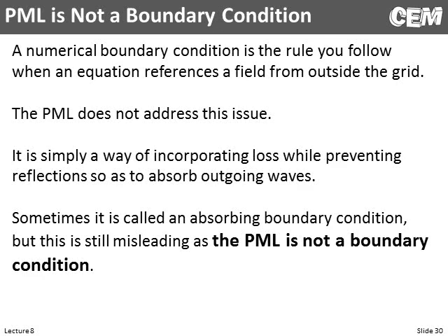The last thing I want to mention is the industry calls the PML a boundary condition, but make no mistake, it is not a boundary condition. It's not a numerical boundary condition or a physical boundary condition. The physical boundary condition being something like tangential fields continuous across an interface. This clearly is not a physical boundary condition. A numerical boundary condition, we're talking about an equation at an outermost cell in a grid that needs a term from outside of the grid that isn't available. And so how you handle that is what's called a numerical boundary condition, or just boundary condition when we're talking about modeling. So the PML is routinely called a boundary condition, but it doesn't answer that question.